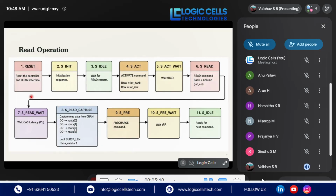Next, coming to the read operation, it is the same as the write operation: reset, initialize, idle, then activate, then TRCD is executed. Then the difference is that the read operation is executed, where bank plus column is done.